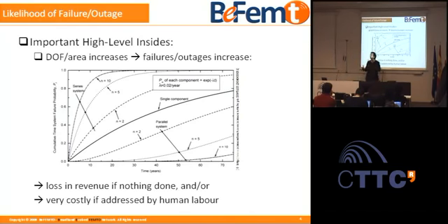The probability that your system goes in outage or that your system fails is essentially directly related to the number of components you have, and the probability of a single component going in outage. So I'm taking one of the typical slides from this operational design. You plot the probability of failing of a single component versus time in years. A component can fail with a certain failure rate, given there. It's just an example to give you an idea. That probability over years goes up.